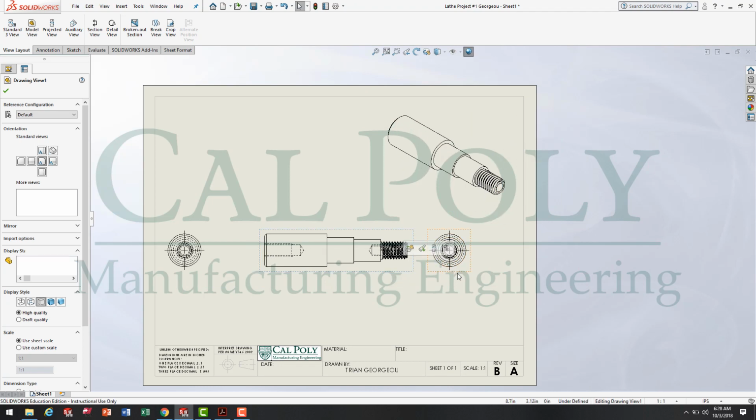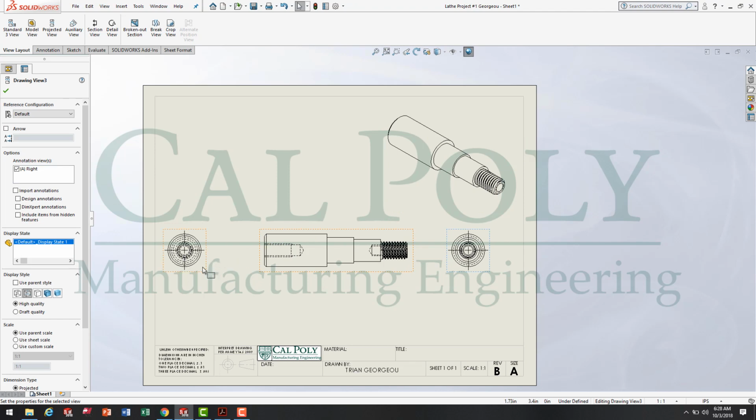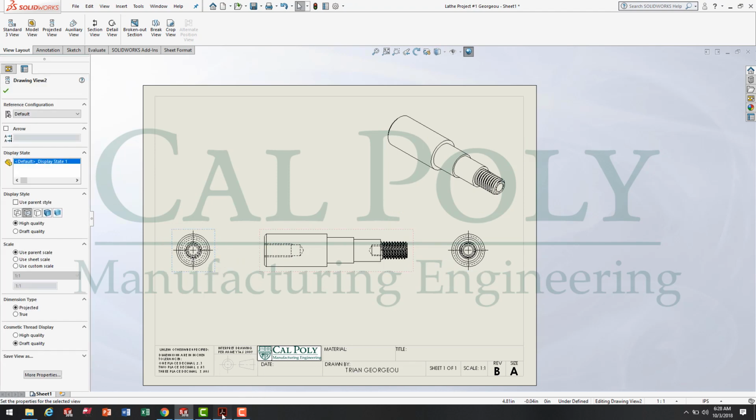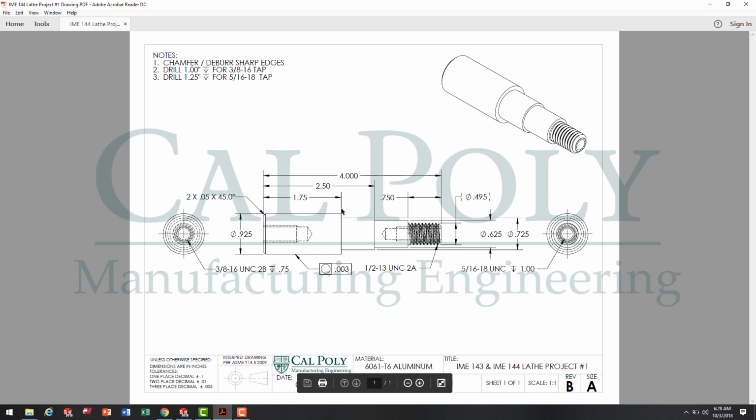So at this point, I'm going to go through and create all the different features you see on this engineering drawing. In fact, the first thing I do is I place my center lines and center marks. Notice the drawing in the manual is missing a center line. So we need to go ahead and revise this drawing and put it in the next revision of the manual, as well as put a center line on the drawings that you're going to turn in class.